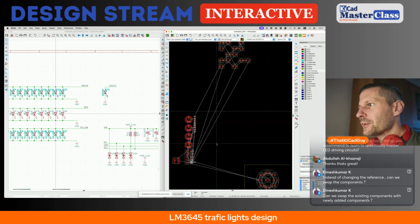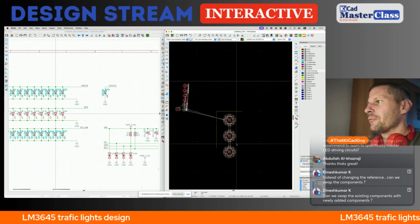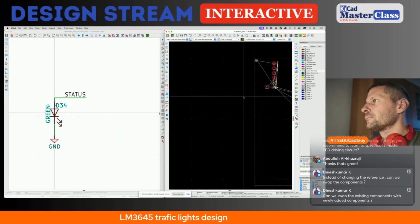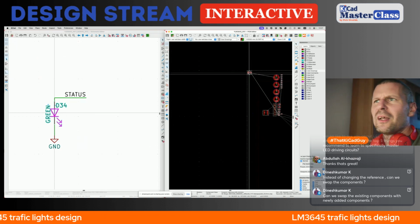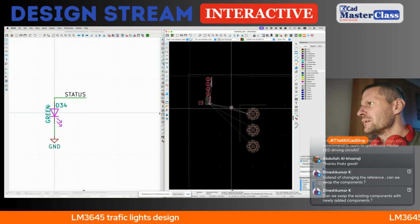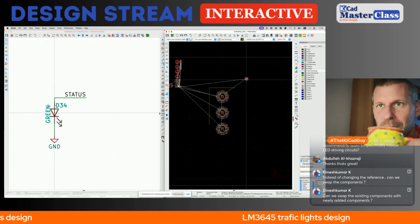What we need is the signature of the connector. So now we have placed all LEDs. Let me update the PCB from the schematic. Okay. And yeah, there is one LED. What's this? This is the status LED. This will be somewhere near the driver.